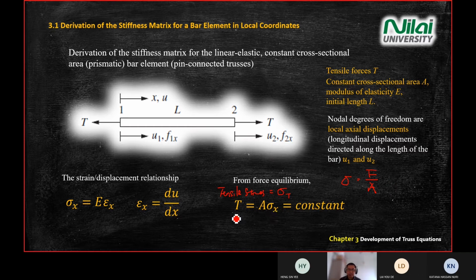So you want to find the force. So this is a tensile force. Sorry, just now I mentioned this one as stress. So what you do is you rearrange the equation. Your force equals stress times A. So this is a force.